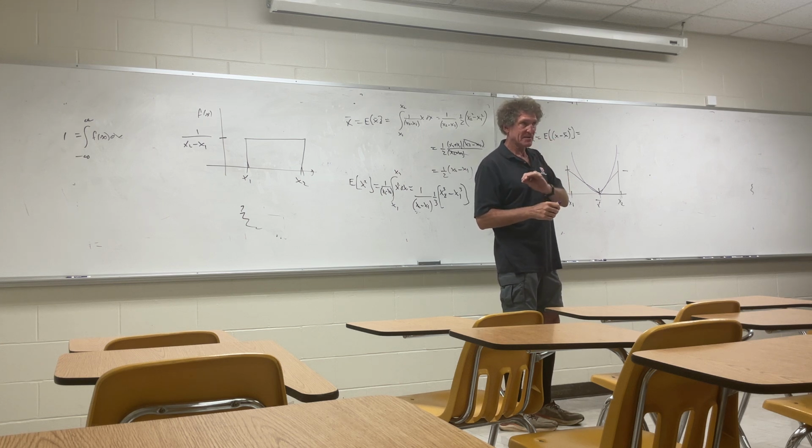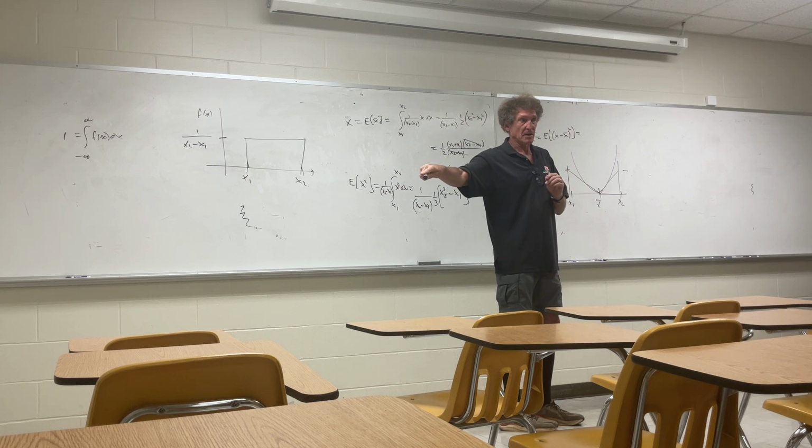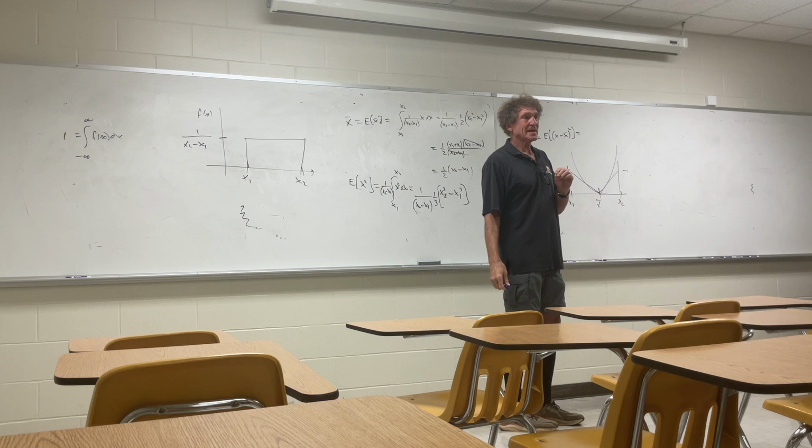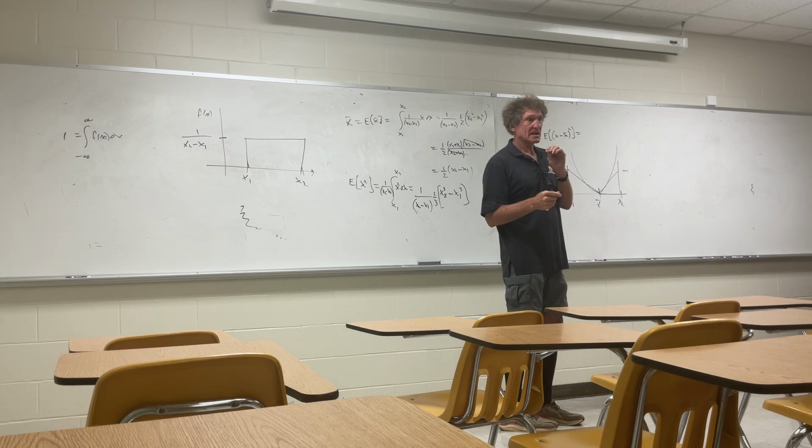I'm getting to a point where we're going to apply this to quantization error. Have you heard that term? Anytime you have an analog signal that can take on all possible values, a sine wave for instance, and you have to make it discrete levels, it will be a 0, 1, from 1 to 2, and so forth. That's called quantized levels. When you have that, you introduce error, called quantization error. But if you minimize the quantization error, you really don't even know it's there.